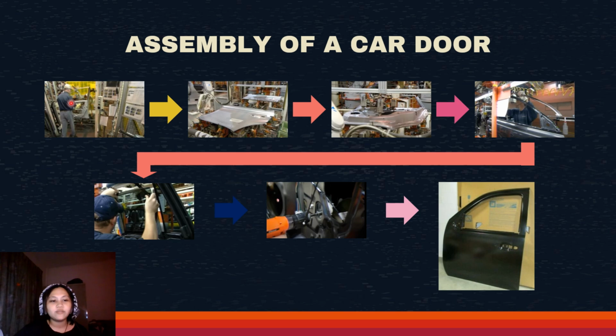The car door frame from the earlier process is then placed over the bars and tubes. A robotic platform angles the parts to weld them together, forming an inner panel of a car door. Next, another robotic platform applies adhesive to the rim of the outer car door panel. Mechanical fingers of the robotic platform then dab adhesive at strategic locations where it matches up the tubes and the steel bars that are constructed in the inner panel as they combine it with the outer car door panel.